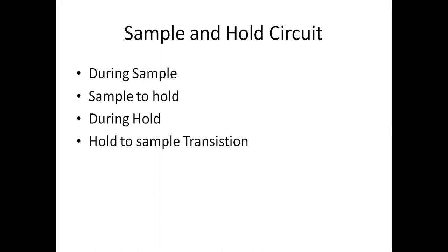So for a converter, in order to accurately measure the voltage at a specific time instant, a sample and hold technique is used to capture the voltage level, and it will hold it long enough for the measurement to be made. In the acquisition of such a time series, a key role is played by a sample and hold module.